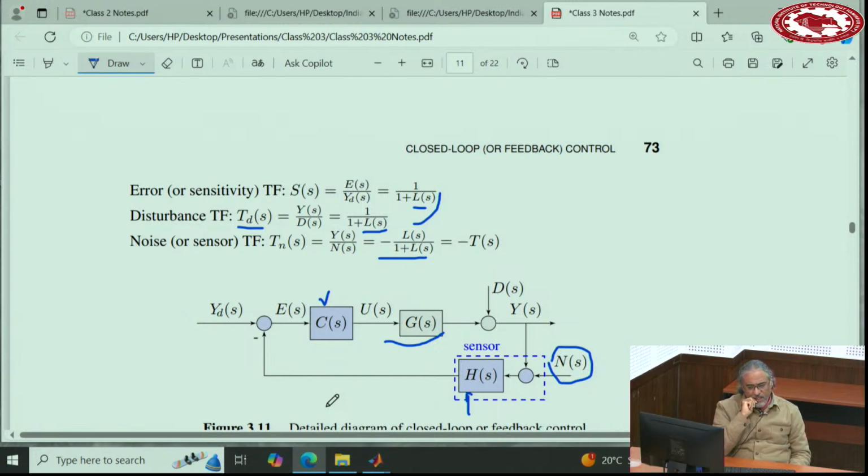For gain margin, we say, if I don't know this whole thing exactly, and it can go up or down, especially on the upper side, how much can I increase this before the loop becomes unstable? That is called gain margin. People have realized throughout the years that these two margins, phase margin and gain margin, are very convenient, very important, and very informative to give a good indication of how robust your control system is. One of them talks about delays in the loop, and one of them talks about changes in the gains of the system.